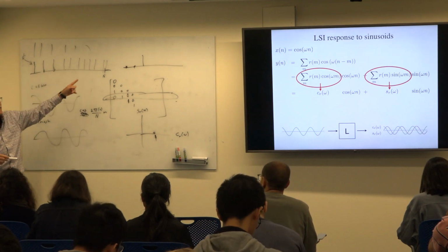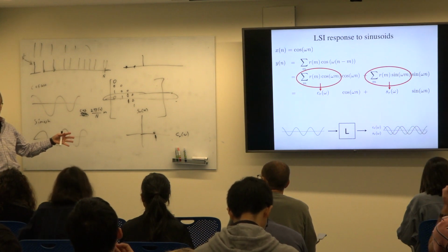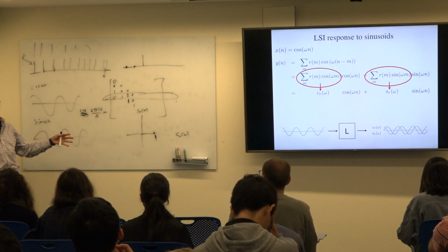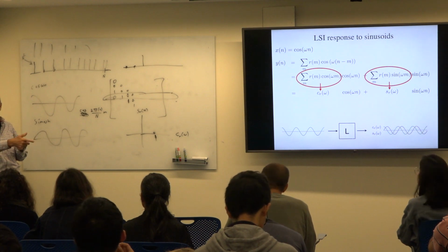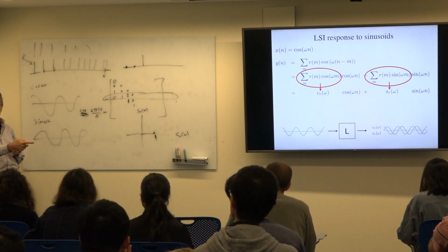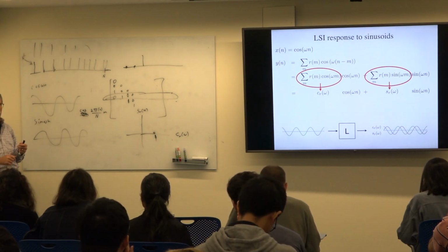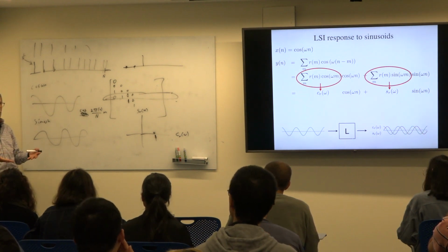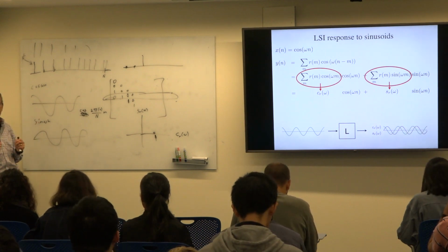Another way to think about this thing, it's being convolved with your input, which is to say you're averaging lots of your input, which is you're blurring your input until there's no form left, and all there is brightness. So if you think of the input as an image, fine, we've only got one dimension, so image is kind of funny, but it's a one-dimensional image. If it has any pattern in it, any bright spots and dark spots, goes through our system, they're gone, because we've taken an average of everything and just output the average. So we've blurred it to smithereens. But if I take the whole image and make it brighter, that brightness will remain, because I'm retaining the average.